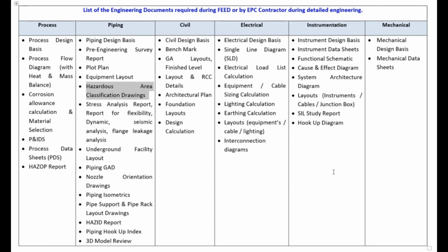It is like, for example, closed system, open system, okay, hazardous system, non-hazardous system. So based on that, the hazardous area classification drawings are developed, and why it is essentially required is, whatever the instruments, whether it's electrical instruments or the instrumentation control items, whenever you are putting them in a hazardous area, the equipment should be usable in hazardous area. They should be explosion proof, flame proof.